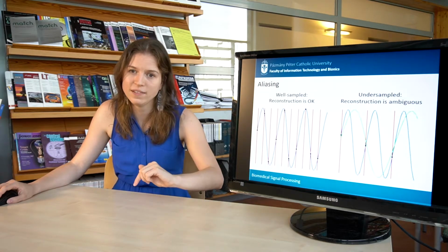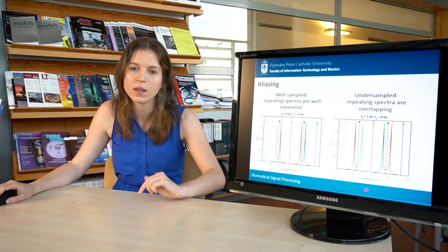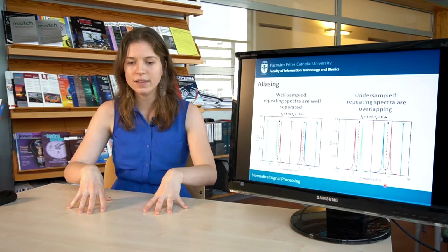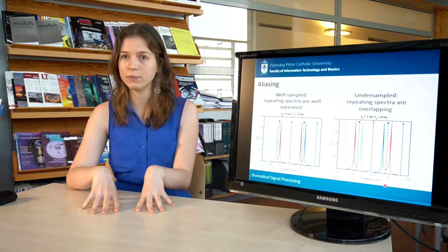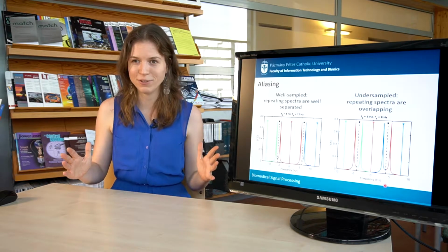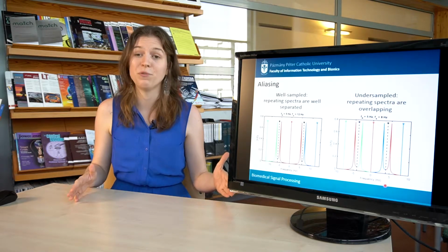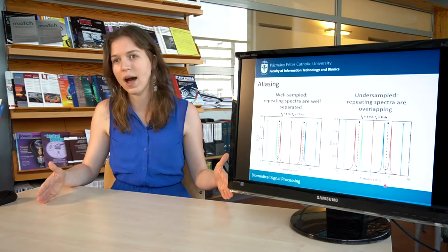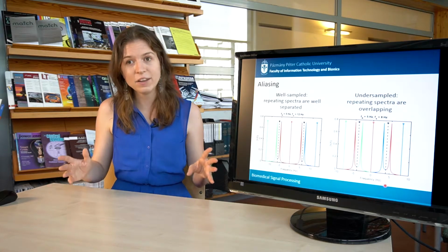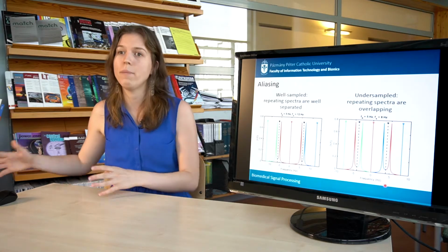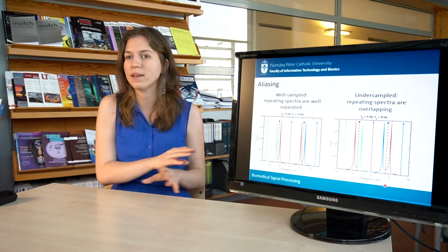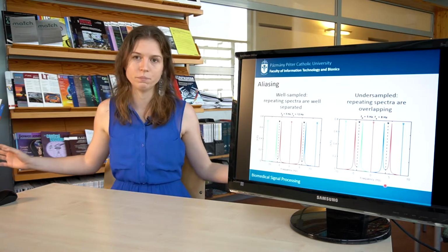From a frequency point of view, what is happening? So the FFT, the fast Fourier transform, is actually periodic. So we usually plot only one period of it, from minus half of sampling frequency to half of sampling frequency, and that's all. But actually, in theory, it is periodic. So it is repeating periodically. You should put them next to each other until infinity.